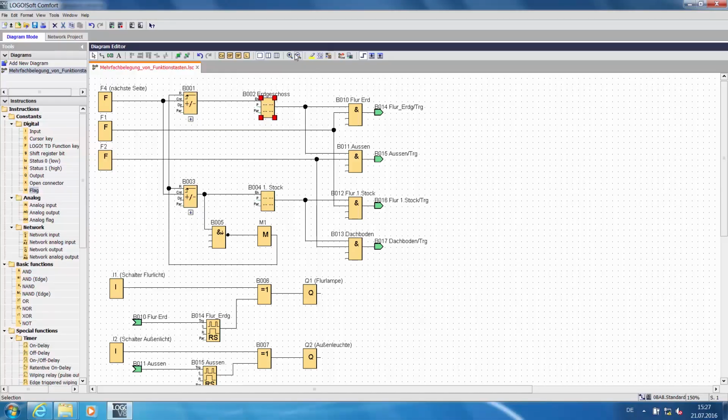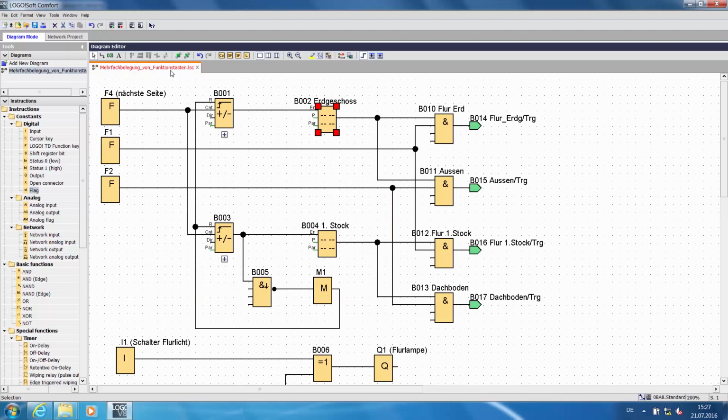In the upper part of the circuit, we see the program part for the message texts. Here there are 2 message texts which can be alternately operated via these counters. If I wish to operate more switches, I in turn have to activate more counters. With the F4 button on the text display or on my smartphone, I can then toggle between the respective message texts.